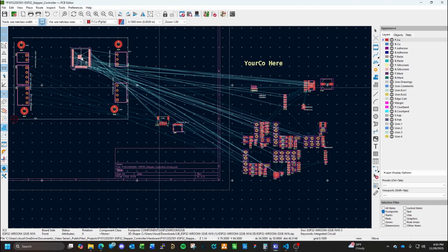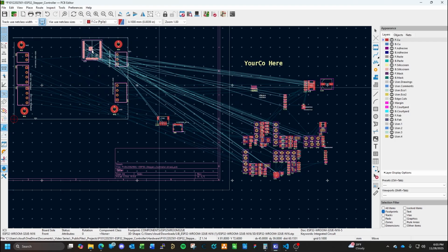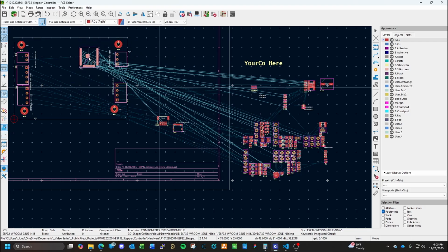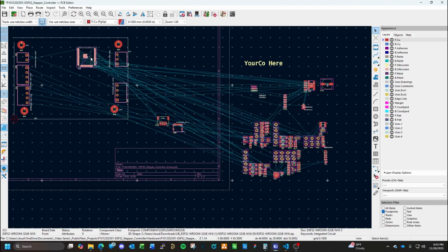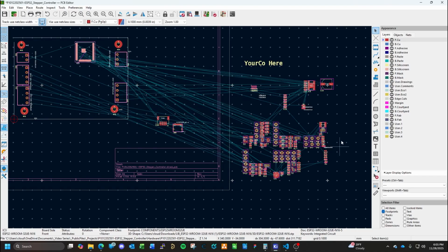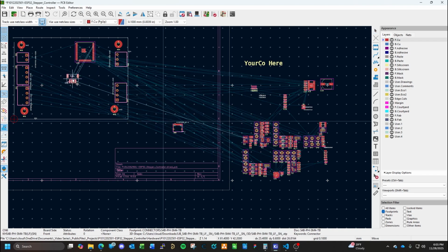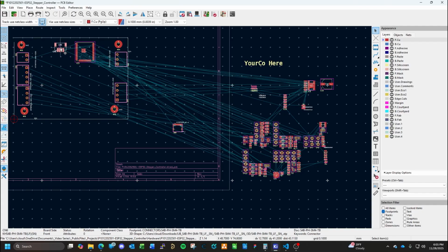Let's say we want the ESP32. It doesn't have to be against an edge because it's got the IPEX antenna on it, but it's probably easier if we do. Let's just plan for that. We'll want the USB port. Now, since this is for programming, here's where the interesting thing comes in. If we're going to throw this in an enclosure and strap it to a DIN rail, hopefully all the programming is done.